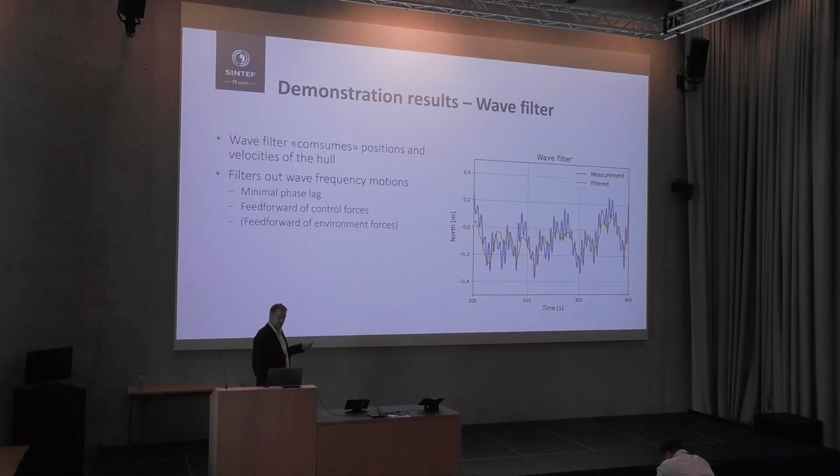In our case, we didn't connect this directly to the environment, but it's very common to have a feed forward, where you have a measurement in the environment and feed it through a force model into your wave filter to recover phase. But this is, call it, a simplification in our model. It's not anything to do with the specification in the environment. But it works quite well, and in the simulation, the DP controller works to keep the vessel in place in the environment, compensates for the forces experienced by the vessel.